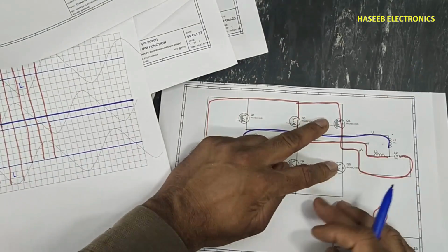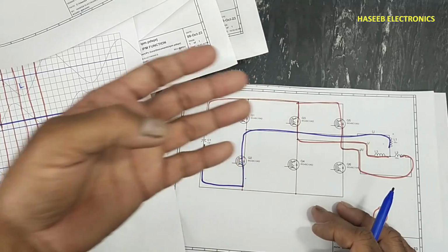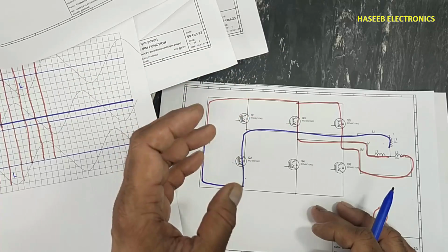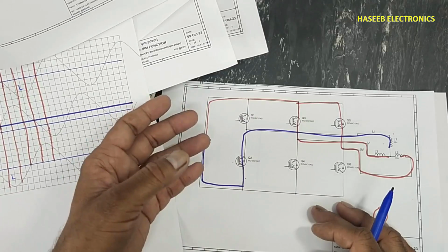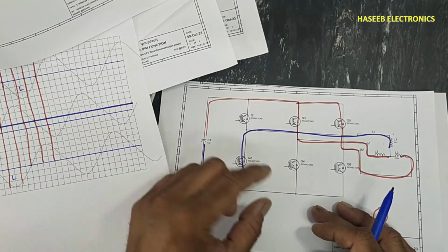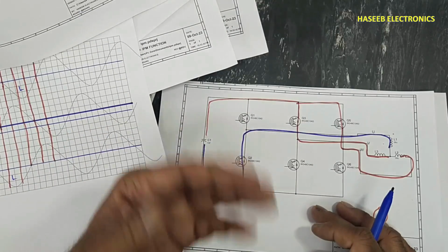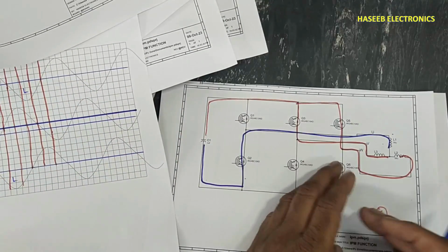These timing signals are coming from the microcontroller. In the software, in the source code of the microcontroller, these timing signals are defined and their time is variable based on our required RPM of the compressor.